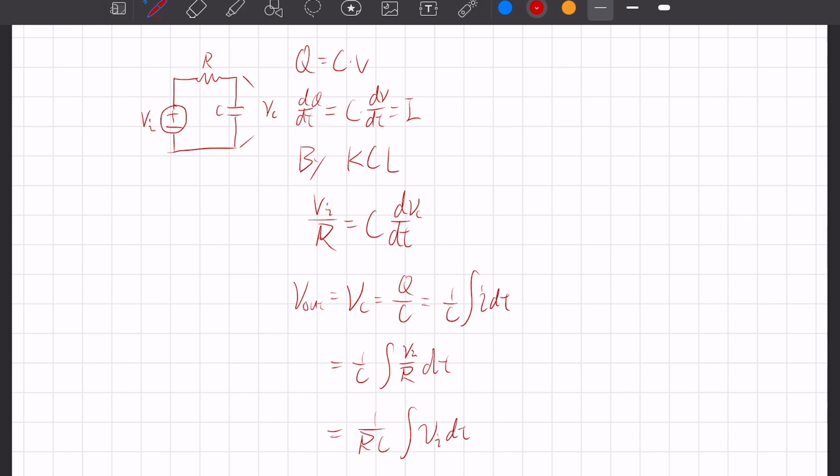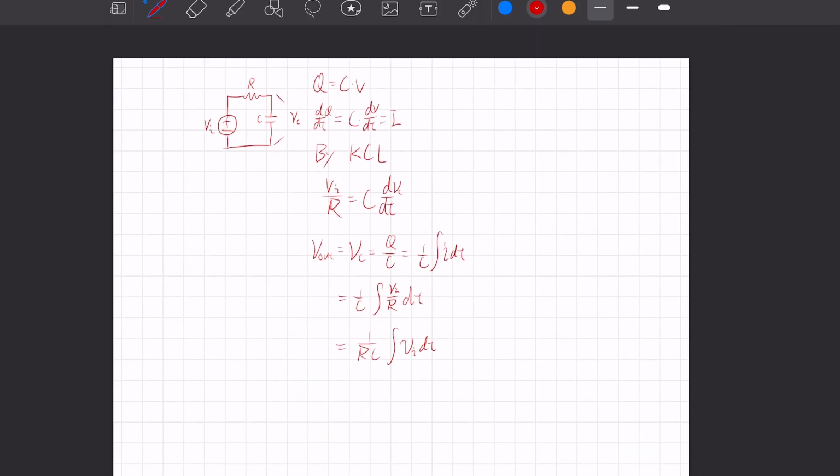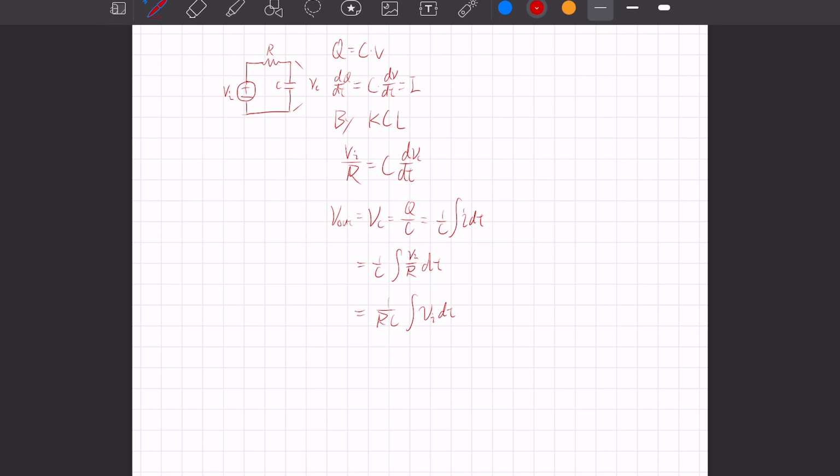But we still find that the output voltage of the above circuit is too small, so we will use an amplifier to amplify the voltage. According to the amplifier's formula, it can be used to adjust the output magnification. By the simulation results, the output voltage amplitude of the RC circuit is about 0.6 volts. We probably need a magnification of 10 times.